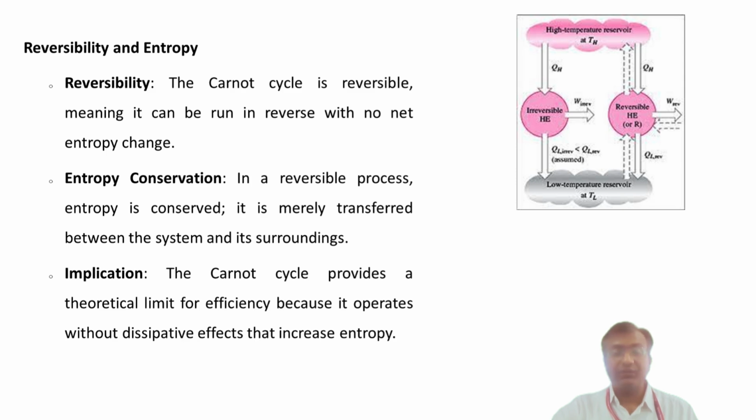the entropy change. The work done by the engine is QH minus QC. From the entropy perspective, QH is equal to TH into delta S. We are modifying this formula and putting in this. In the Carnot cycle, delta S for the system is QH by TH and delta S cold for the system is minus QC by TC. So this is a closed cycle. The net entropy change of the system is such that delta S hot is equal to delta S cold. Therefore, QH by TH is equal to QC by TC, leading again to the efficiency formula, which is given by 1 minus TC by TH.